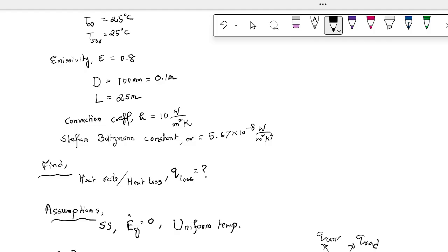Temperature Ts to the power 4 minus T surroundings to the power 4. Perfect. So now here's the thing. If we're going to use degrees Celsius in that equation, it is not going to work. We're going to convert it to Kelvin. Does everybody understand that? So how do we convert that temperature to Kelvin?